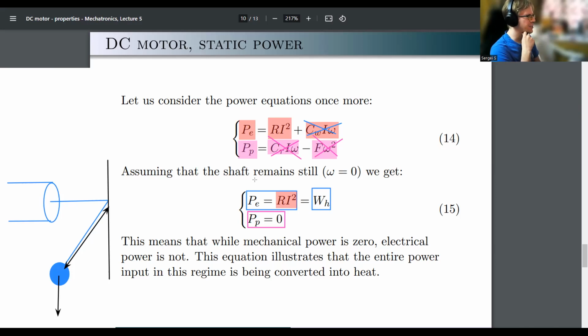There are various ways to negotiate this. One that is very popular in practice, I guess, is to have non-backdrivable gearboxes. This will be the type of gearbox which completely negates the payload. The motor wouldn't feel anything.